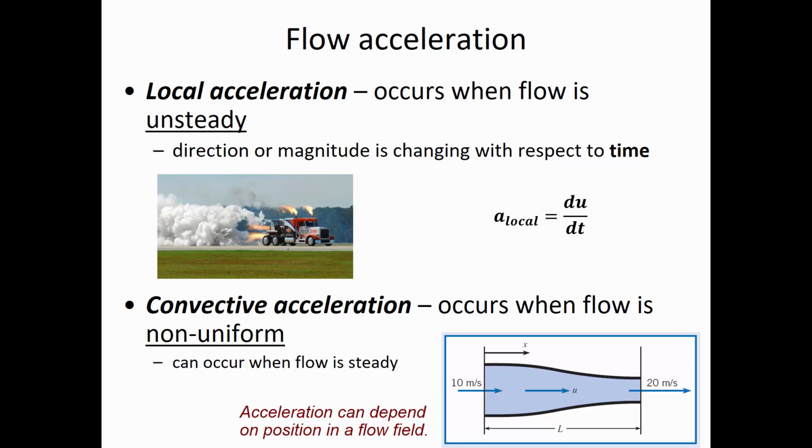What was our old equation? Back in Chapter 2 and Chapter 3, what formula did we use to predict changes in pressure? Change of height, gamma, right. So what was that equation called? Oh man, you guys flushed your memory right after the exam, huh? Hydrostatic, yeah, good. So the hydrostatic equation was the first way that we had to predict changes in pressure. But the hydrostatic equation only works when conditions are static.